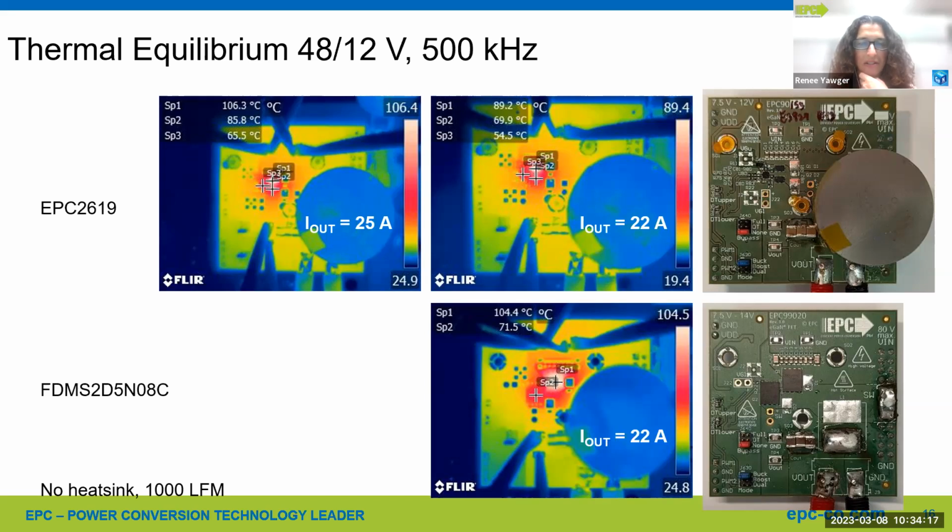In your example, we can see that you can improve, I think it means increase, the frequency, but does using GaN, are you also able to reduce EMC noise? So EMC noise has lots of sources, of course. We think that you can have very effective designs with GaN even at higher switching frequencies, and there's a few factors in it. Of course, the actual slope is the first thing people think about. When you switch fast, you've got to have faster rise and fall times. And of course, they contribute to higher frequency spectrums.